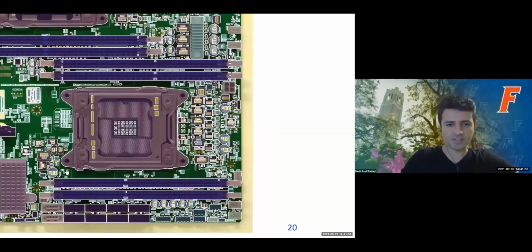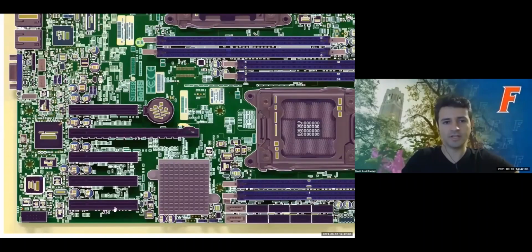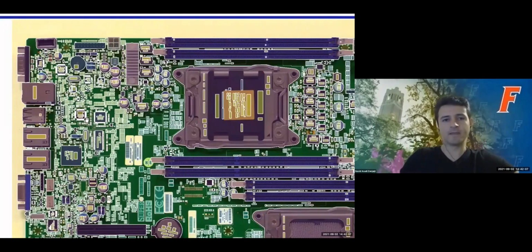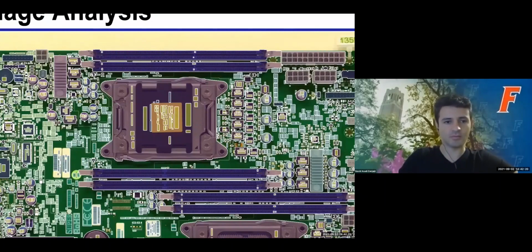Whether it's a reference designator, which is basically a marking on a board that says what component is what, whether it is a pad where it doesn't have a component on it, right? Whether it is the pins of an IC. It has been shown that sometimes these pins may be missed. So the component is all good, but the pin may be missed or desoldered, which can be a modification and eventually cause a problem.